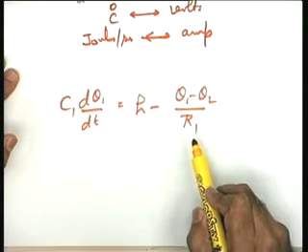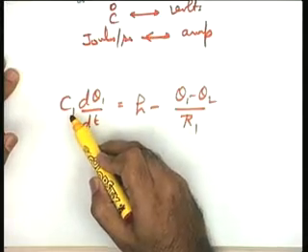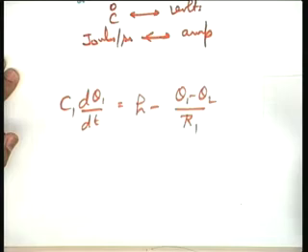And now onwards, if you understand this point, I need not take up these variables in terms of mass, specific heat, film coefficient, area and all that. I assume that given a particular situation, I will be able to get the values of thermal capacitance and thermal resistance, and therefore the dynamical equations now onwards could be written directly in terms of C's and R's, if this point is very well taken here.